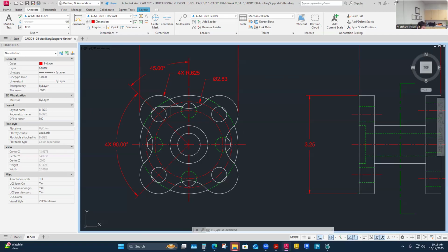And this is great. This is probably the way I prefer to do a lot of this kind of dimensioning. Polar coordinate location dimensioning is kind of my go-to on this. But also ASME will allow you to do rectangular coordinate locating dimensions. And so I could rectangularly coordinate or locate these holes and radiuses.